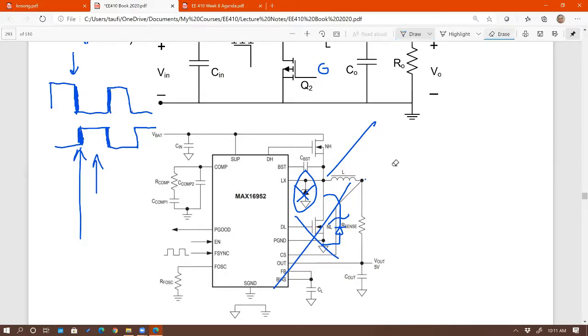So that's why you need a path for that inductor current to kick back and freewheel its energy. It is kind of interesting because in the first place we got rid of this Schottky with the MOSFET, but then at the end, you have to add that Schottky back.